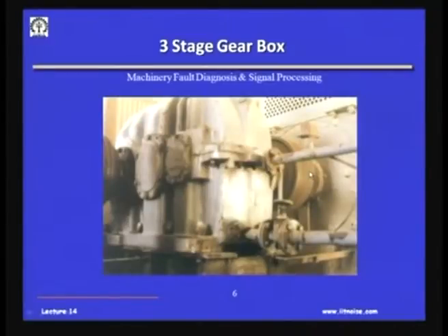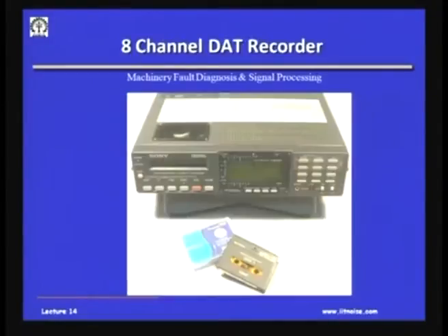And because of, I would say, defects, because of obvious reasons there are certain defects. So, we put accelerometers at the bearing locations and accelerometers near the foundations, and we took the measurements of these vibrations simultaneously. And obviously, this analysis, as I was telling you, Cepstrum cannot be done in real time on the fly. So, we have to record the signals in a DAT recorder, wherein you can record almost 8 channels of vibration simultaneously to a bandwidth of 20 kilohertz.